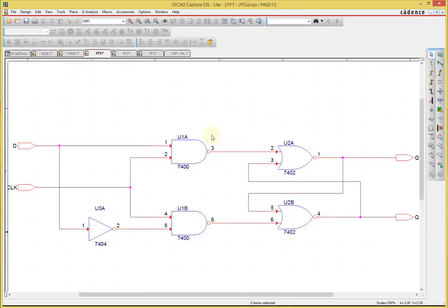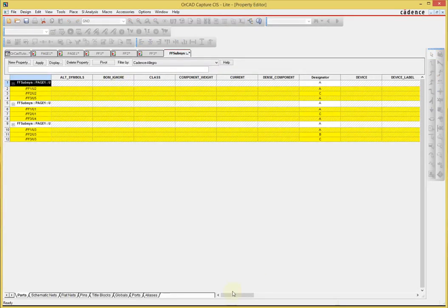Let's go in there and start with the 7400s, 7402, 74. So let's start with the packages. Okay, how? Oops. Control Z, select, holding Control Shift, Control E. Again, PCB footprint. I need to specify a footprint for these parts. So what do I write in here?